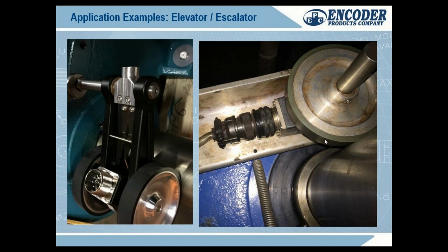They were doing that because this shaft is huge. This wheel is 12 inches in circumference, so it's a little less than 4 inches in diameter. So what's this shaft? 5 or 6 inches, I'm guessing. There's not a lot of through bore options for encoders out there that are greater than 2 inches. There's some rotary scales that get into the 500 millimeter range, but they're very expensive. They're not for something like this. They're for positioning rotary tables.